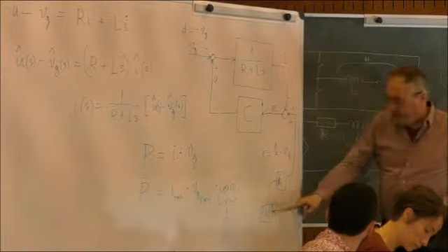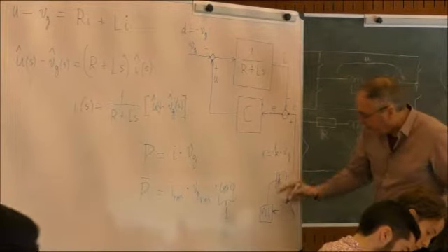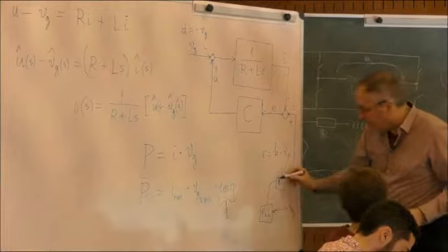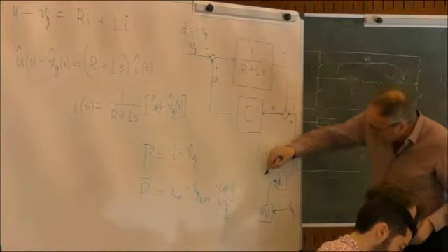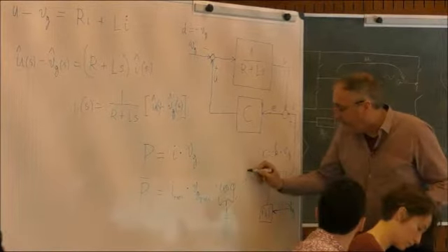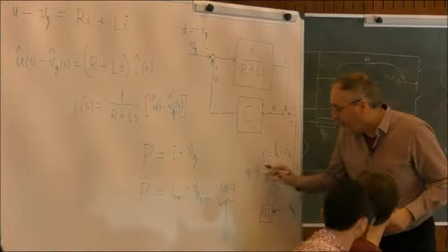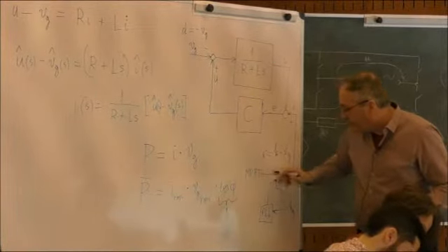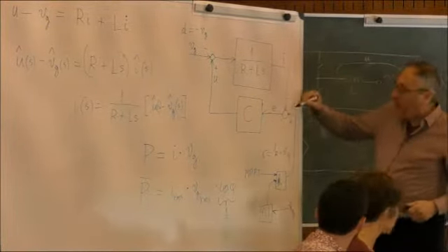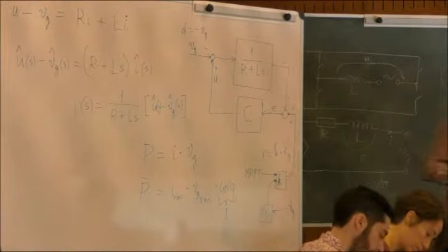So the grid voltage enters the PLL, and the output is only the fundamental component, which gets multiplied with this k. This k is controlled by what is called the MPPT algorithm, the maximum power point tracking. And then it gets to be our reference signal.